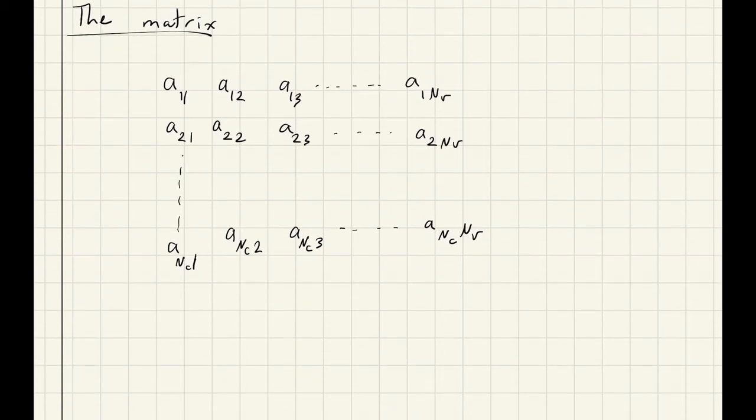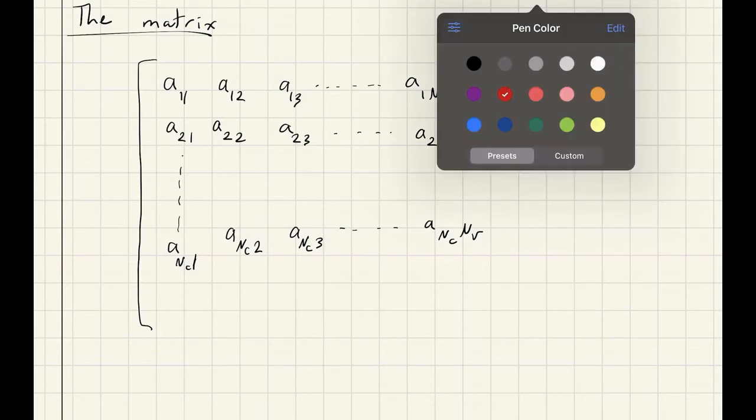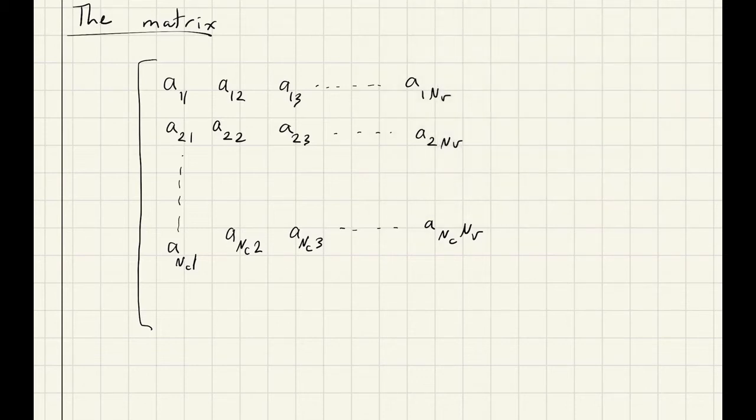Well, we also, not to forget, have an additional unknown vortex, which is the newly shed vortex. So we have an extra set of influence coefficients, related to the effect on each collocation point due to that new vortex. And then we'll just call this A1 new to indicate the new vortex.